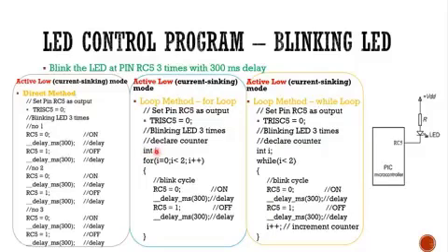However, if you're using the loop method, you can see here, by introducing a counter, we have the variable I, integer I, starting from 0 to almost 65,000, so very large. Because the counter only needs to count up to 2, it is better to use char or short, because it is less than 2 counter. That one later on. Right now we declare variable I as integer, and for looping we are using a for loop. For I equal to 0, and I must be less than 2, and then increment I.